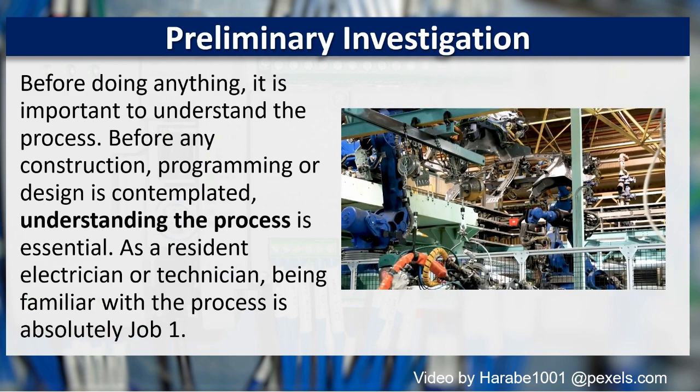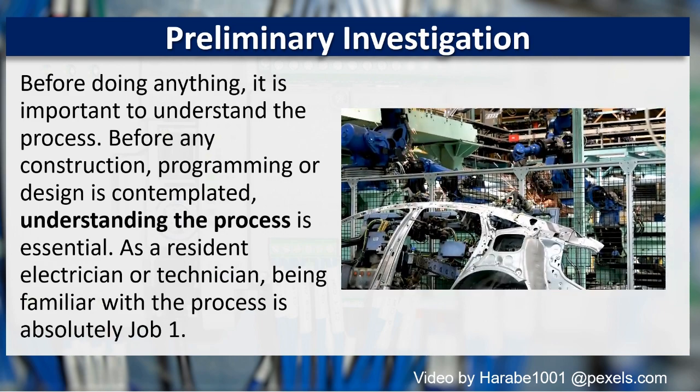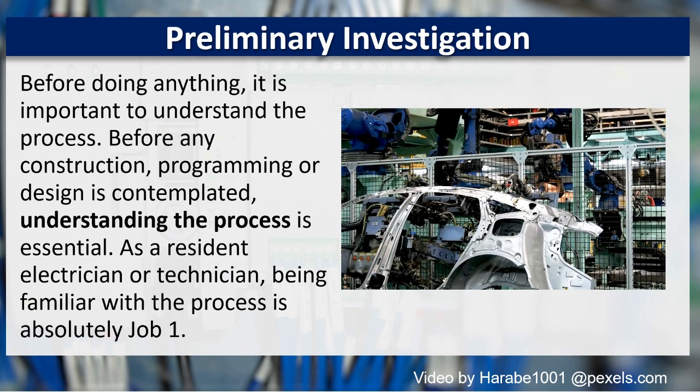With any PLC project, the first thing that you do is conduct a preliminary investigation. Before doing anything, it is important to understand the process. Before any construction, programming, or design is contemplated, understanding the process is absolutely essential. As a resident electrician or technician, being familiar with the process is absolutely job one.